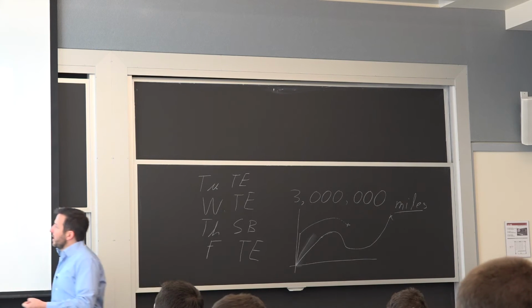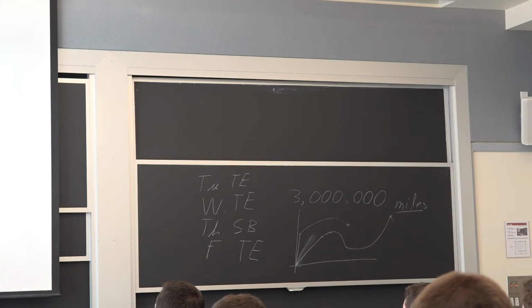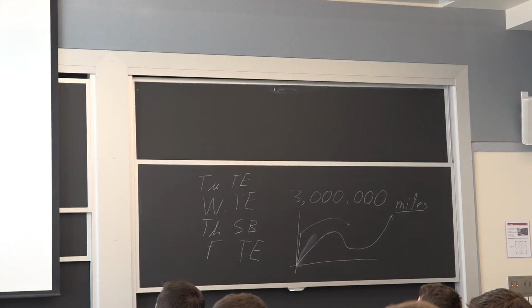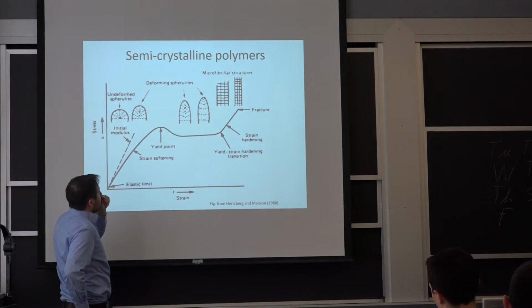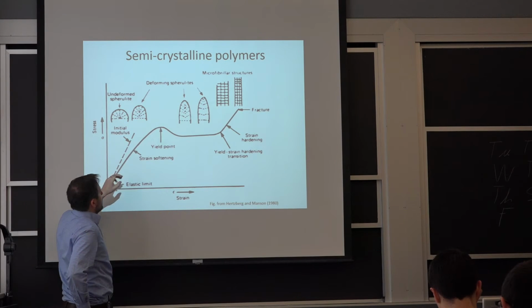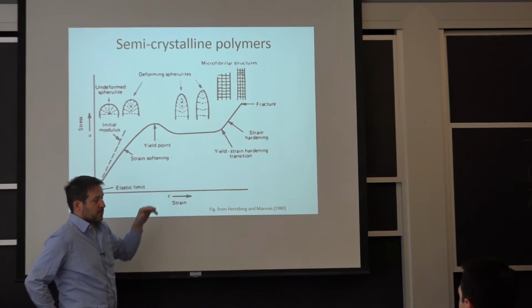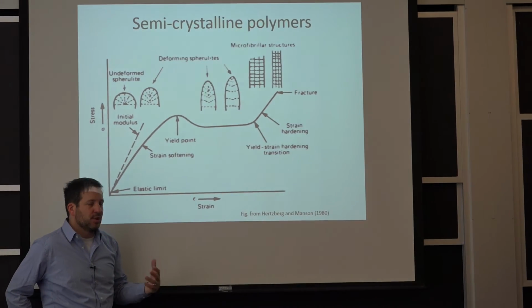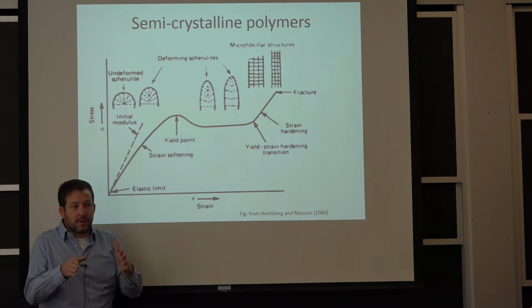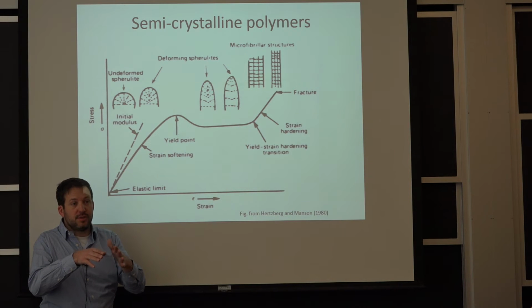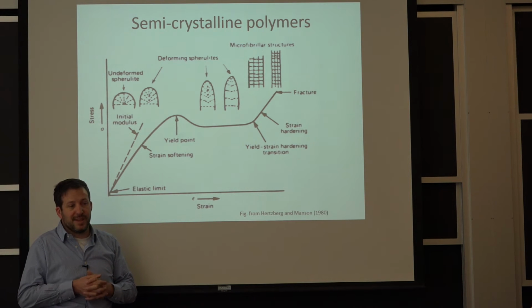In this transformation from this state to this state, it does continue to harden, even if it's a plastic. Now, the main difference is when you have this neck formation, it's related to an instability, so you don't have enough strain hardening, so when the deformation starts to localize, it continues to happen there. That's what necking really is.